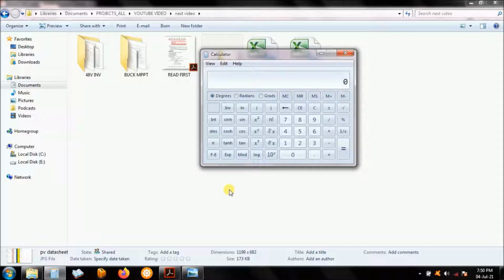Suppose you have a gadget that would maintain the solar module at 18 volts. It means if the module is connected to a 12-volt battery and it's giving you 18 volts, you are actually saying it's 18 volts times 5.5, that is 99 watts, almost 100%. Well, we're looking at plus or minus there.